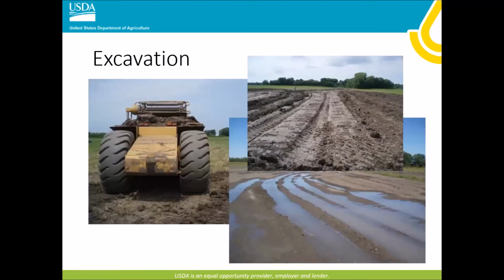One thing I really like to highlight is these macros don't really need to be left with a smooth grade. The picture here was from a macro construction utilizing this large pan, and as you can see, it left big old ruts. Well, it's a wetland, it's wet, no wonder he's going to leave ruts. So there's no reason to push these in with a dozer. Just leave them, as you can see in that lower right picture, there's a diverse habitat from the ruts that were left there with the dry mud flats. Now, from an engineering perspective, this is tough because I want to have a smooth bottom, but that is not needed in these macros. We need to leave these rough and let nature take them back over. Next slide.